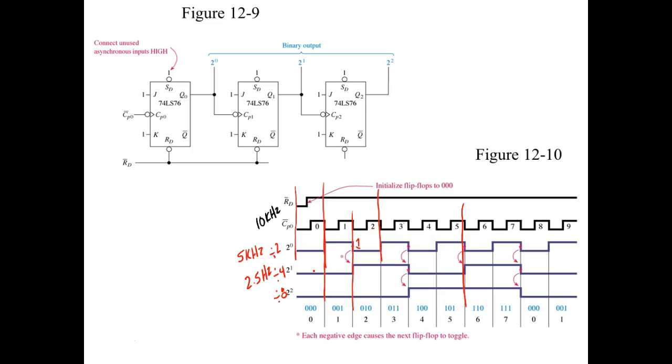So we'll show you how we can set the modulus of the counter. You could take this guy and divide it by 2, or you could take that guy and divide it by 8, and you'll get the same number. So we use these guys as frequency dividers.